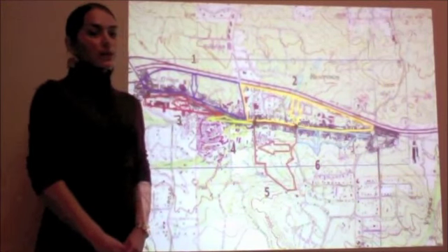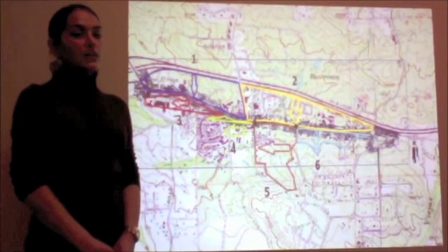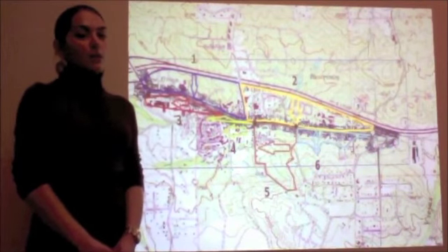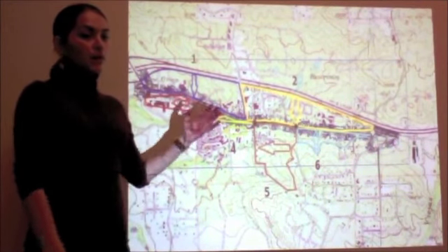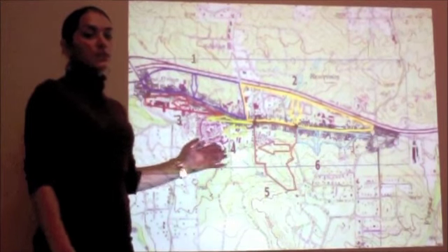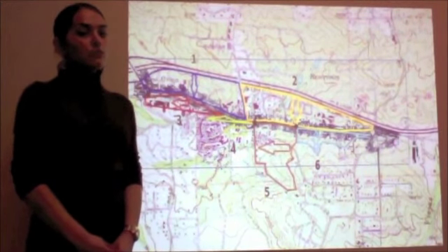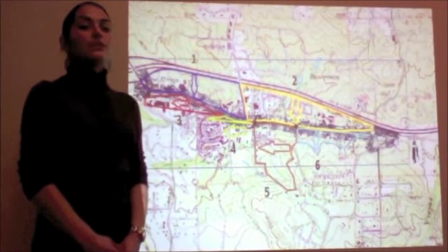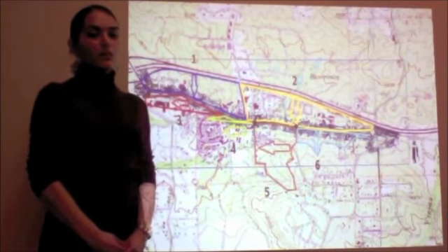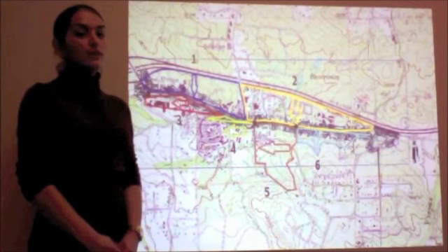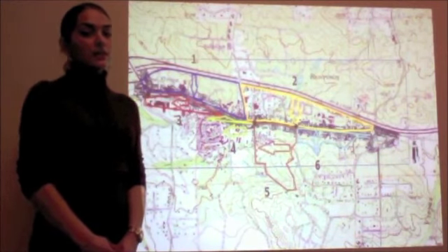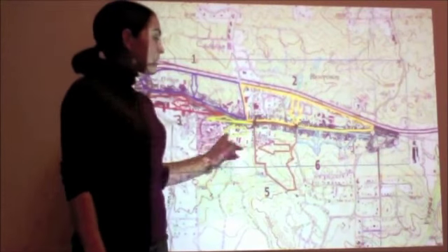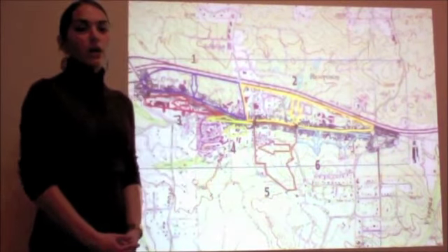Before conducting the rational method, the amount of water basins had to be identified along Alpine Boulevard. First, a topo of Alpine Boulevard was used to identify the location and was placed on top of an AutoCAD drawing of Alpine Boulevard. By doing this, the elevation lines given from AutoCAD made it easier to identify the placements of the water basins. By using these contour lines, 6 watersheds were identified along Alpine Boulevard.